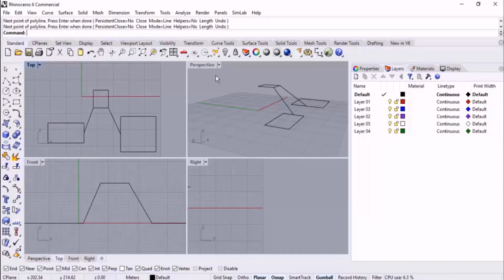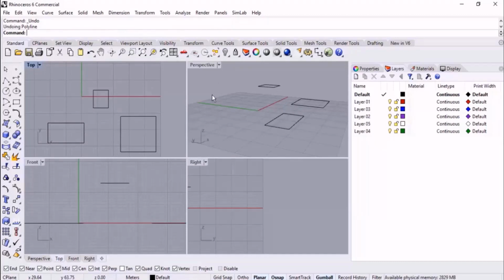As I told you before, project and planar work with each other. In fact, when planar is trying to keep all of the points in the same plane, snap would ruin everything and does not let the planar keep the points in the same plane. In this situation, we can ask project for help, since we need project to handle the situation.